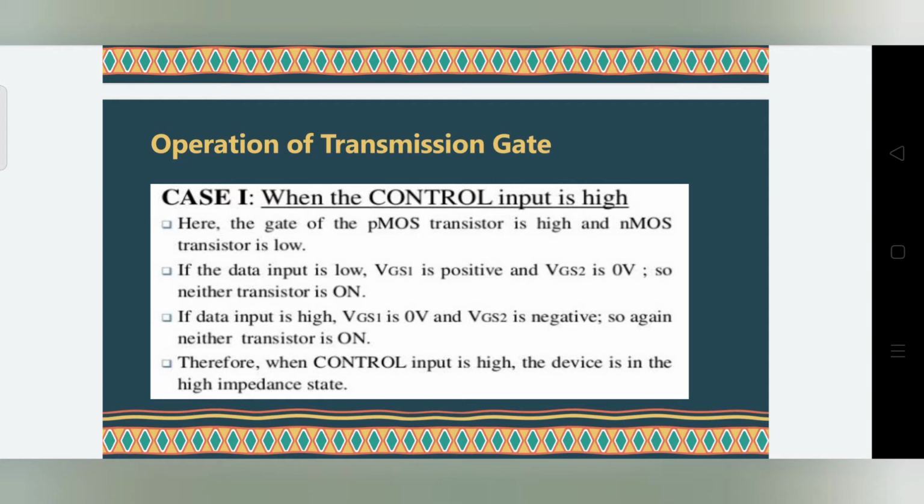The transmission gate is the most widely used solution to deal with the voltage drop problem. It builds on the complementary properties of NMOS and PMOS. An NMOS device passes a strong 0 but a weak 1, while a PMOS transistor passes a strong 1 but a weak 0. The ideal approach is to use an NMOS to pull down and a PMOS to pull up. The transmission gate combines an NMOS and PMOS device in parallel.